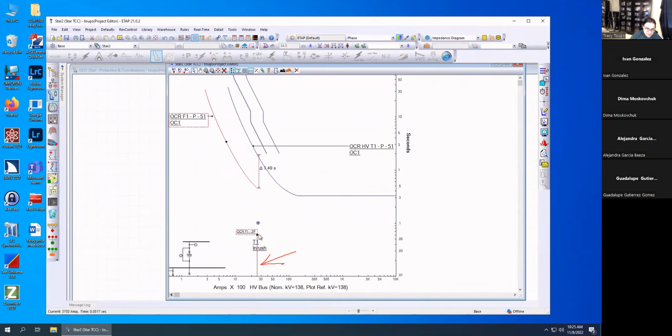And as time increases, it goes up. So let's say we've been online for 1 second. So 1 second is all the way over here. Let me get some drawings. 1 second is about right here. So if I cross-reference that, 1 second will put my dot right here. So at 27,000 amps, 1 second, we're right here, okay? So as the time keeps on going, we're going to keep on going until we hit this point right here. I'm sorry, that's 0.1 seconds, right?